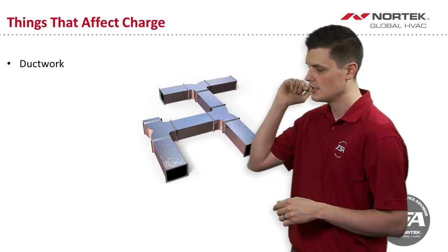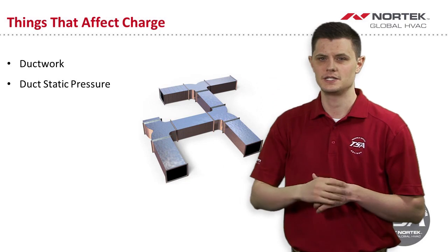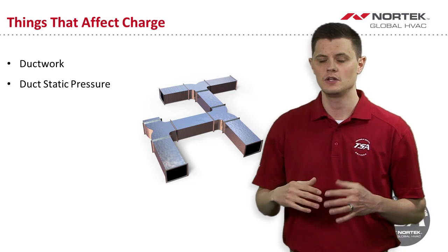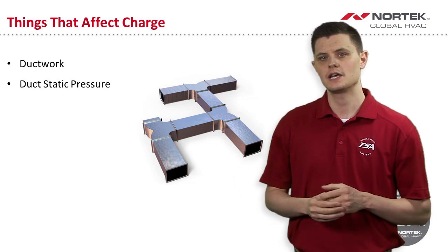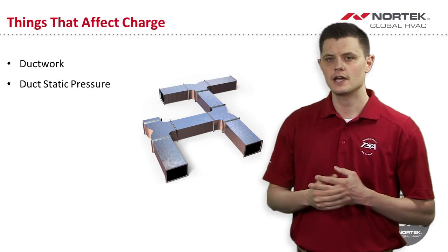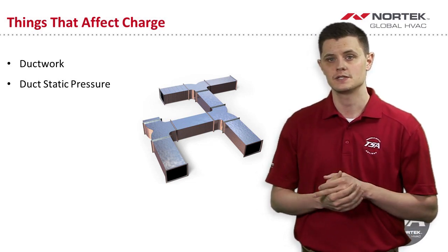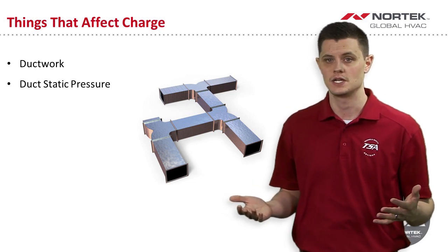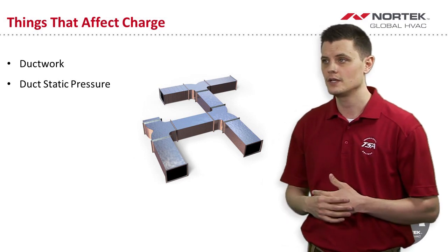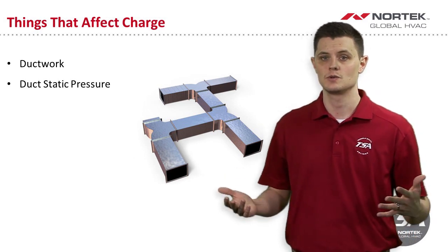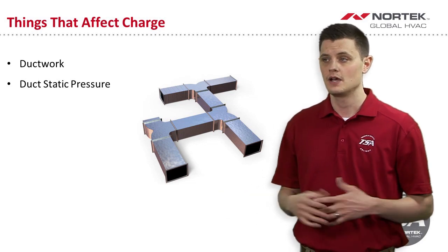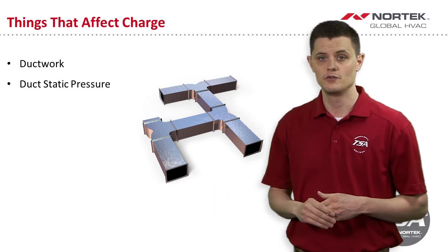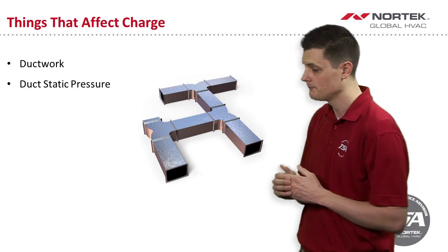So, ductwork, and also take your duct static pressure. If you think your airflow is off, or maybe it's less than what you think it is, take a duct static pressure. Generally in tech service, we go off of 0.5 for duct static pressure if the guy in the field either doesn't have the tools to take a duct static, or doesn't know. But the testing data we have goes up to 0.8 on the duct static, which is high. Anything that is 0.7 or more, you have room for improvement on your duct static number.